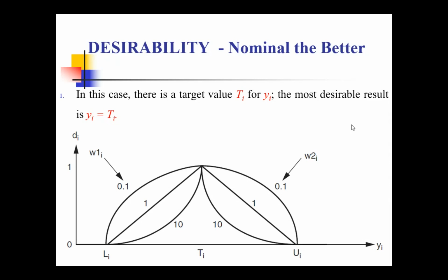For example, if the optimal cutting speed is 180, it will give only 200 as the optimum condition. But in the case of response surface methodology, the exact optimal condition within that range, whether it is 180 or 183 or 179, is possible. So that's why it is more advantageous.